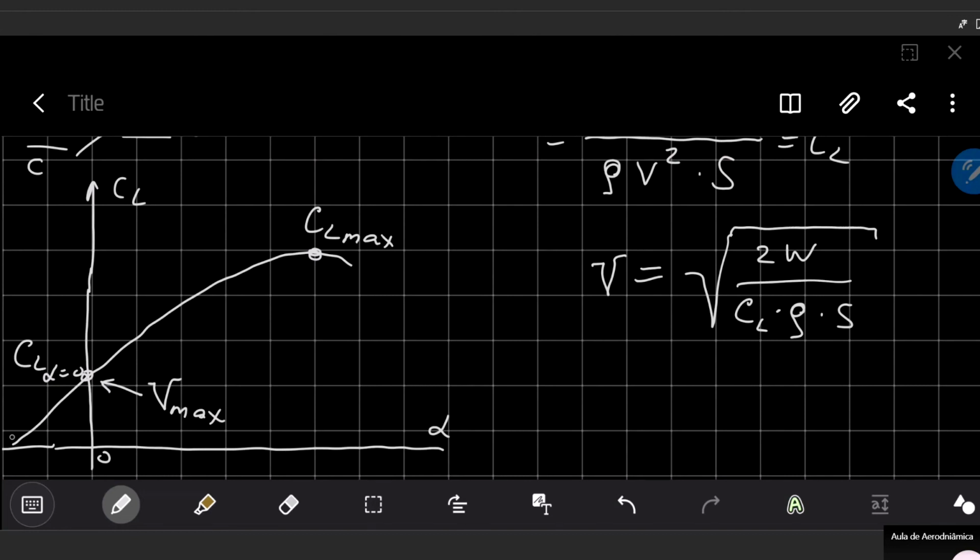I'm not considering negative angle of attack, because if we have practically no lift, the airplane cannot maintain its horizontal flight, it will go down. So most pragmatic is to keep the angle of attack close to 0. So we have a small but positive lift coefficient.